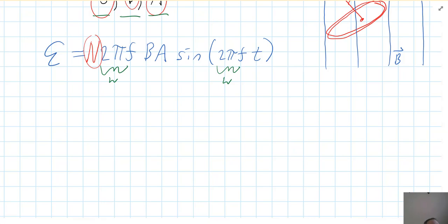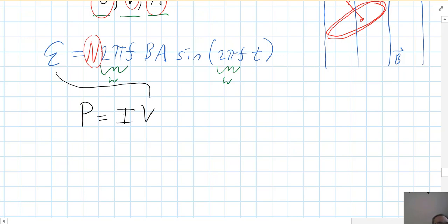There are a couple of equations for power that we know. For electrical power, one equation is P equals I times V. Now remember, E is V; the EMF is just a voltage generated in this manner, okay? I is the current, P is the power in watts. So that's the output, the electrical energy we're getting out of this thing. What kind of energy are we putting into it? Well, we're rotating it. So rotational power, instantaneous, is torque times omega. Technically, it's a dot product, but here we don't have to worry about that, okay?